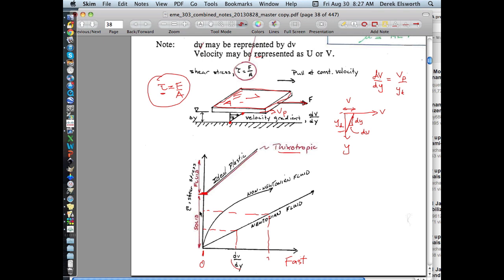Drilling muds are just a suspension of clay particles, sometimes with denser materials like ground up barite to give it some extra density so you can balance the fluid pressures at depth relative to the weight of mud in the column so your well doesn't blow out. But typically drilling muds, if you don't agitate them, become solids. Once you start agitating them, then they become fluids. So they start off, if there's no shearing rate, with some strength.